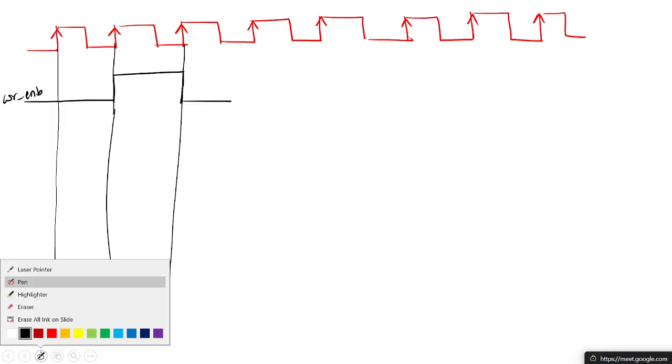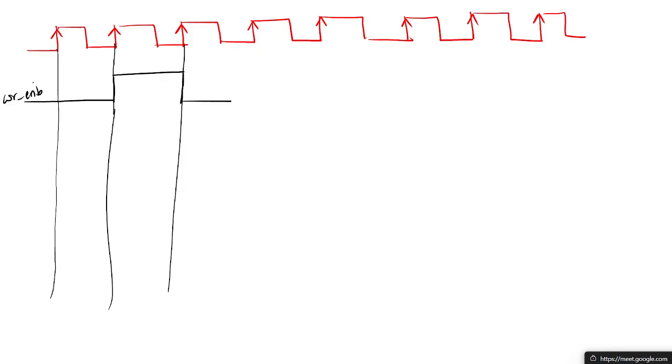After write enable equal to 1, next what I need to do, that means the processor should generate the address where it should write the data. So let us take write address. Write address is during this write enable only. So you have the address, suppose in the 000 location, 3 zeros location, the processor wants to write the data into that RAM.